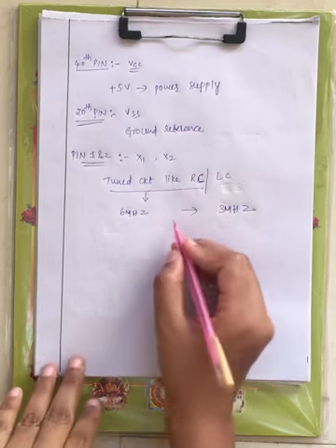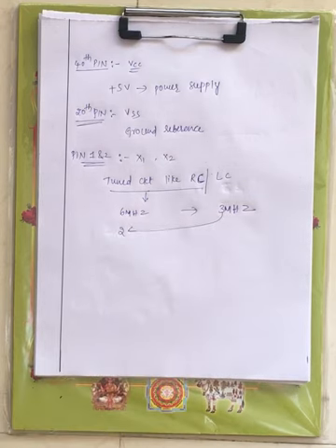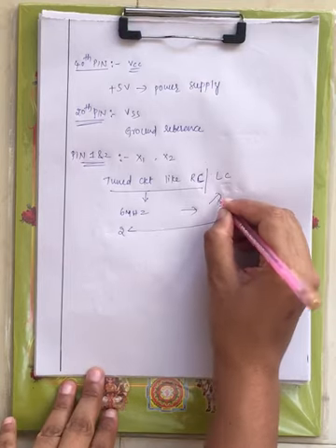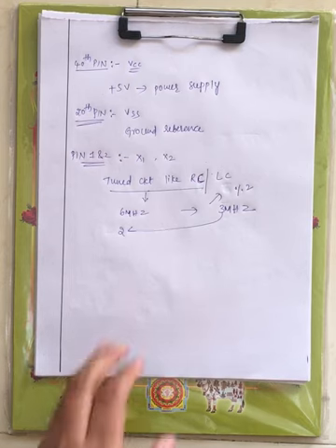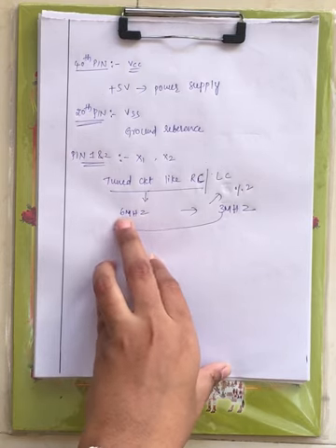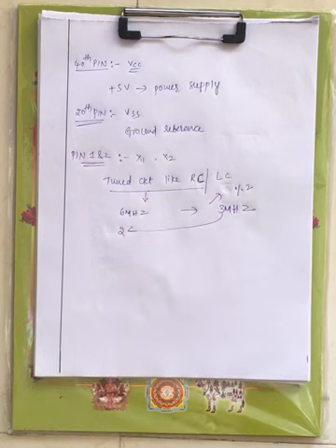That means we have to provide 2 times its frequency, because the internal clock generator divides the oscillator frequency by 2. If you are providing 6 megahertz, divided by 2 will give you 3 megahertz. That means the processor will operate at a frequency of 3 megahertz.